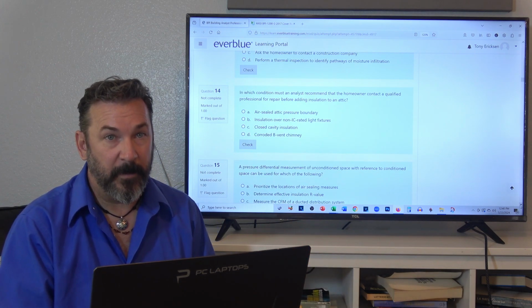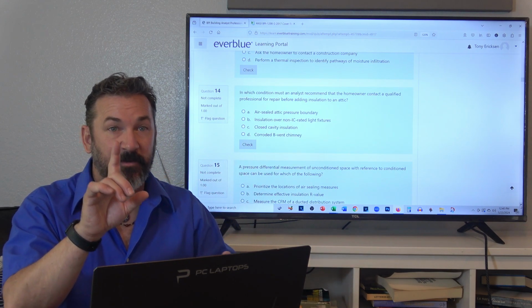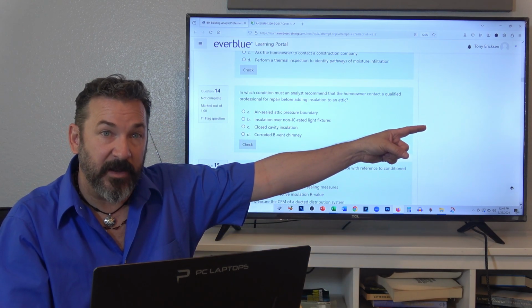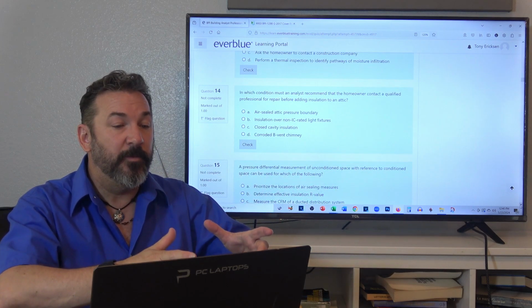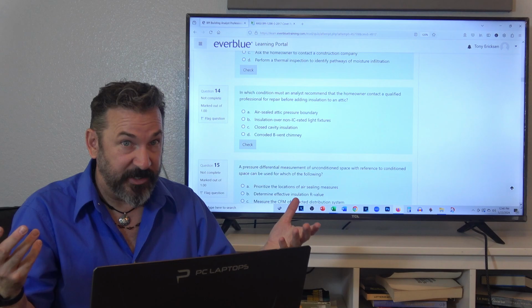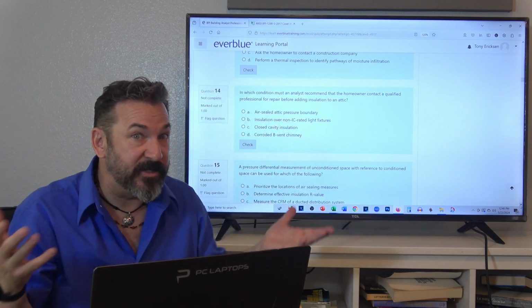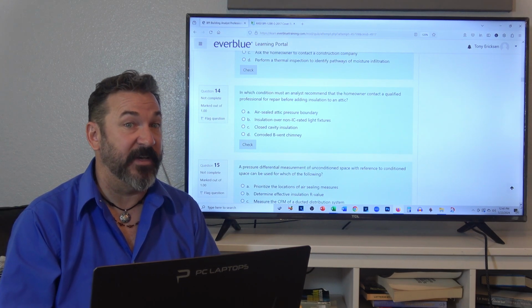Oh, it's sharing a vent with another appliance. No. B-vent just means, it could be a single appliance, but it's just double wall pipe. Like this furnace here has B-vent on it. It's double wall pipe. You can look at it later. But if it's corroded, something's going on to corrode it. There's a weird bend somewhere. I mean, how did it corrode? There's a big problem. Somebody needs to check it out and fix it.